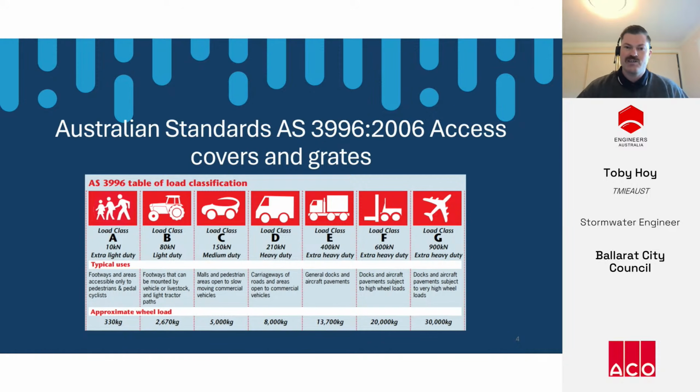For above our drainage structures, we have access covers and grates visible to people. Here we have an excerpt from Australian Standard AS 3996 2006, access covers and grates. This standard specifies load cases and gives them a class rating. Manufacturers typically design covers and grates to meet a specific load class.